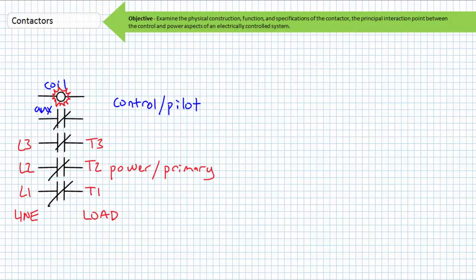The contactor for electrically controlled systems incorporating motors is analogous to the solenoid-operated valve in an electrically controlled hydraulic system. The solenoid-operated valve conducts fluid power, but only at the behest of the low voltage control signal. This is the coil from A1 to A2, supplied not by the high voltage source used to start a motor, but rather the low voltage control signal. The low voltage control signal could be 24 volts DC, 24 volts AC, or 120 volts AC as representative examples. This is the brains.